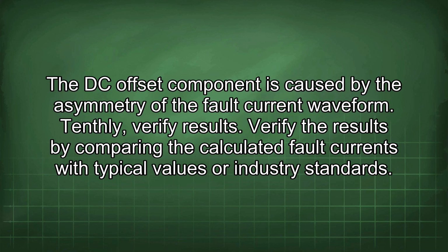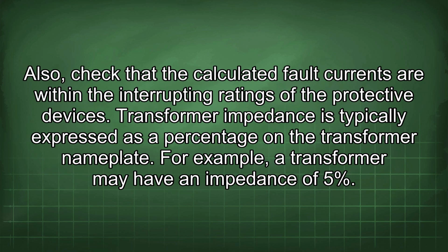Tenthly, verify results. Verify the results by comparing the calculated fault current with typical values or industry standards. Also, check that the calculated fault currents are within the interrupting ratings of the protective devices.